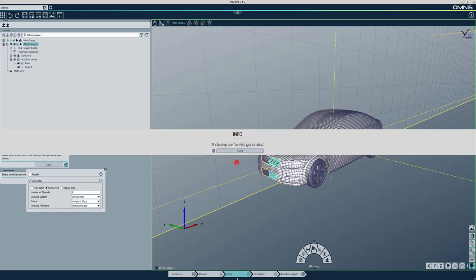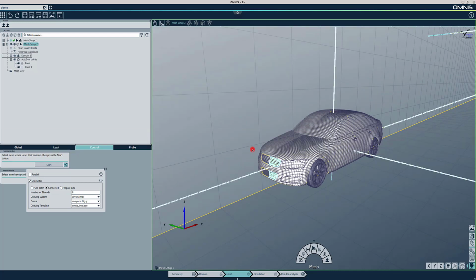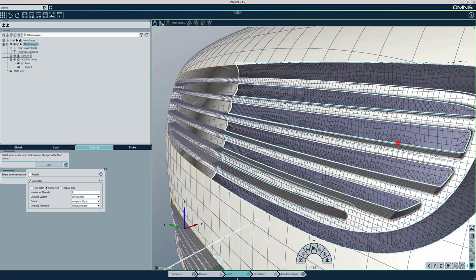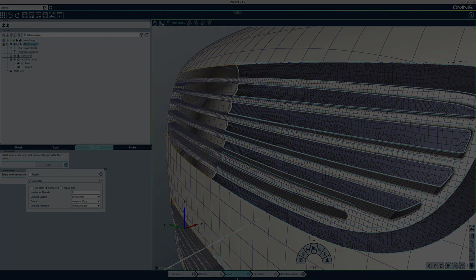The advantage of running AutoSeal from the meshing context is that you can close holes of varying sizes in different locations depending on the local mesh refinement levels, instead of imposing an overall minimum hole size. However, the setup may take more time depending on the needed number of local refinements.